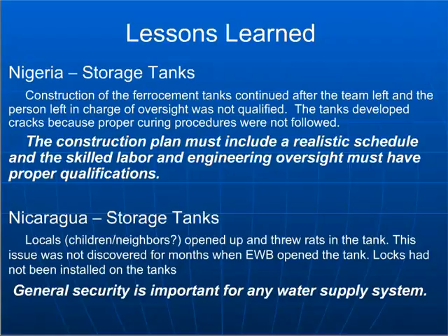A few other examples as far as lessons learned goes. Again, the issue with the ferrocement tanks: the team got down to Nigeria, started construction on a tank, and left the project for the local masons to finish. They didn't quite follow all of the proper procedures, and suddenly cracks were opening up, and it turned out to not work well at all.